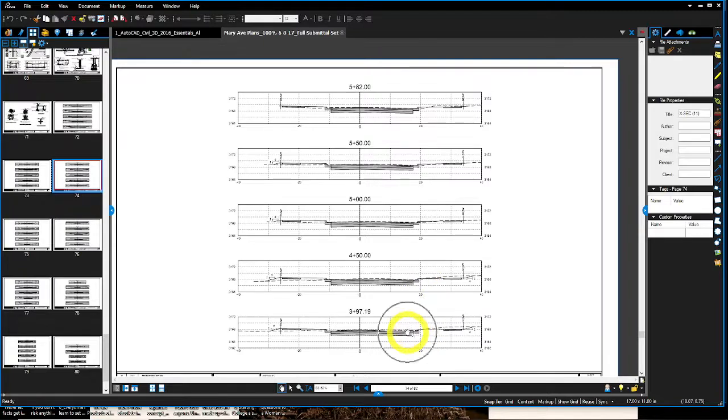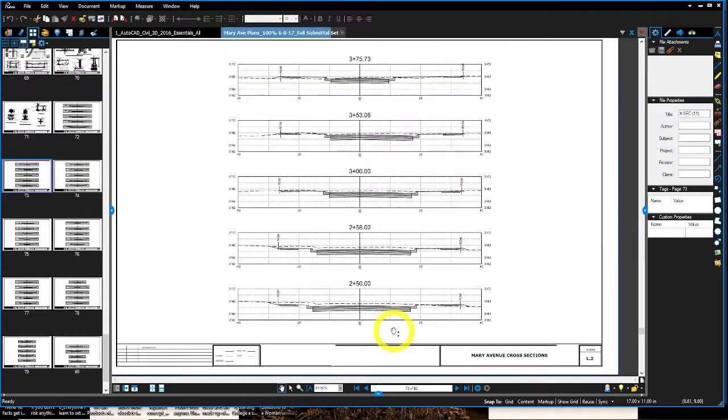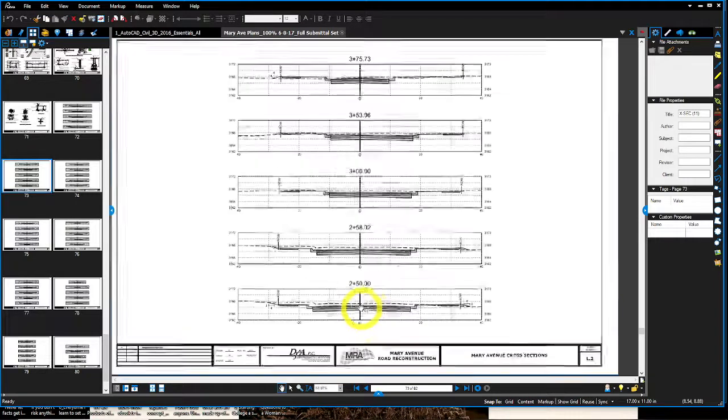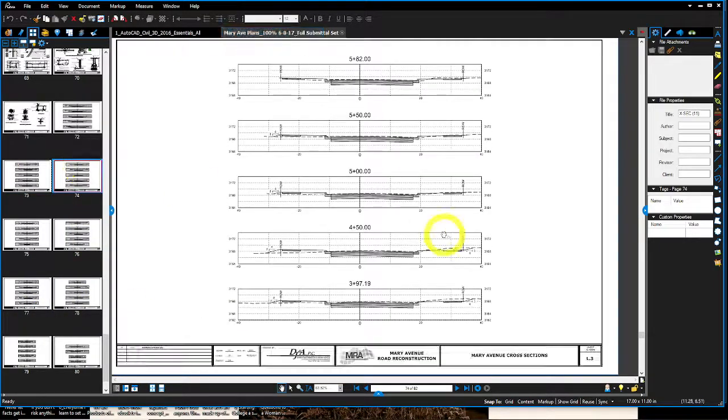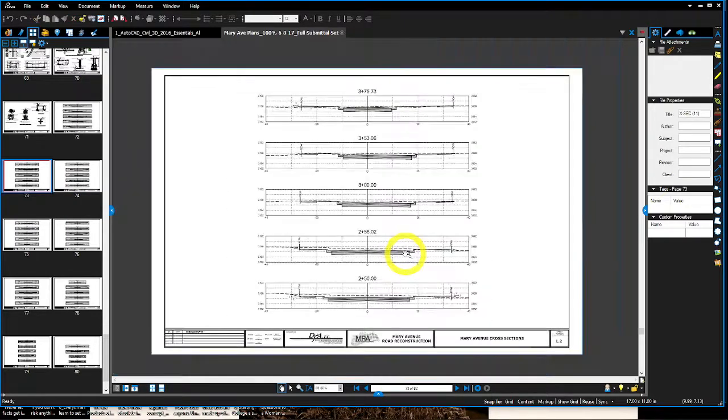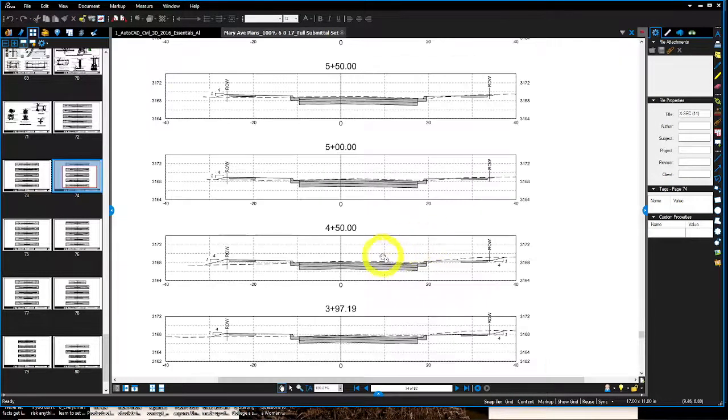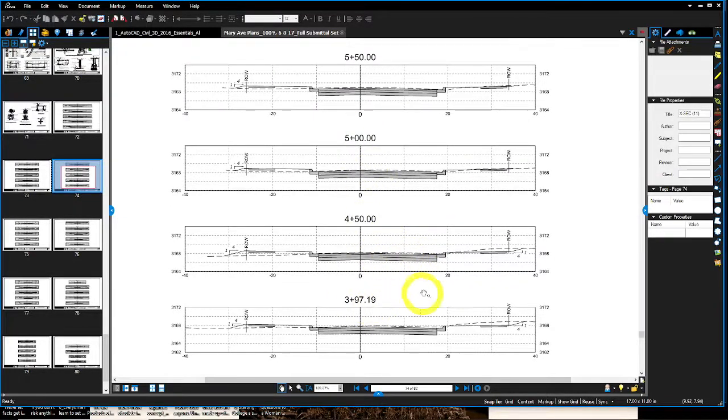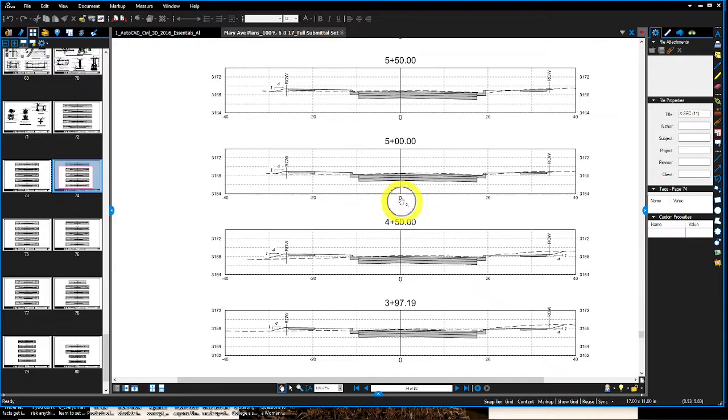So that same plan profile view I was looking at in the top-down view and also in the Z dimension view in the profile view. This is the slice into the road near where I was just at on the last sheet. So here is the section view. Oop, I keep moving around the wrong direction there. Near where I was, we were doing these at a pretty far spread, or 50-foot intervals at max between our section views, but you can see they're hovered around 0, and they go to the right and to the left.